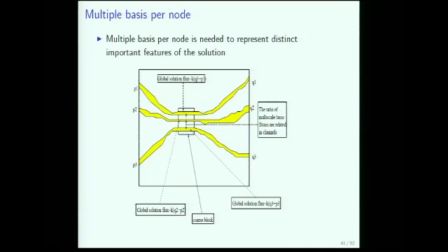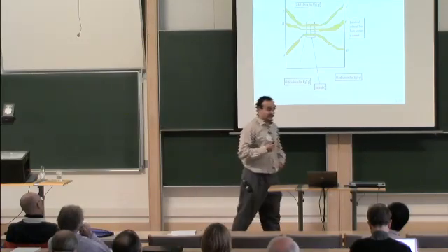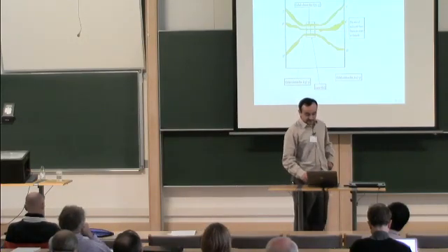Since you can impose any boundary condition you want at the coarse scale, you can always come up with an example where you get all possible pressure values inside for the solution, and you will not be able to get them with your one single basis. So you need multiple basis functions if you'd like to have an accurate coarse scale approximation.